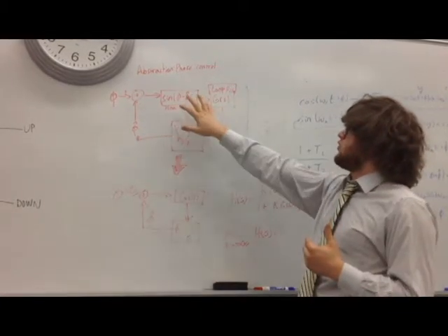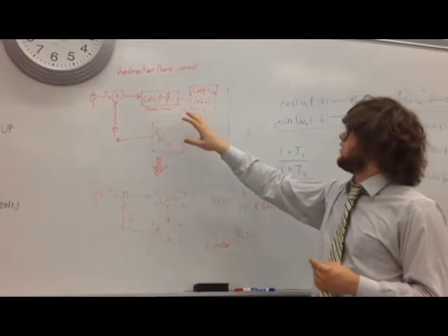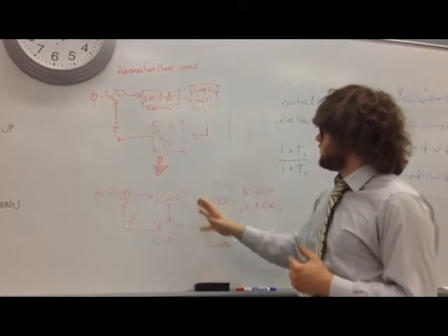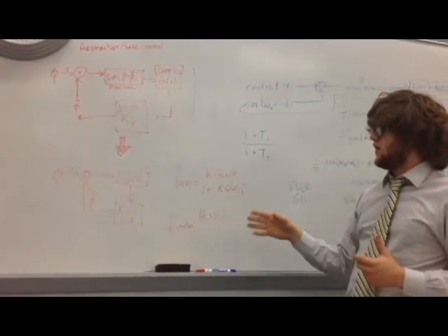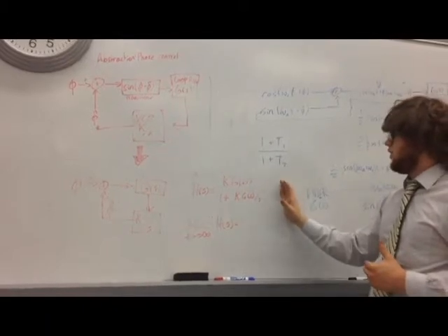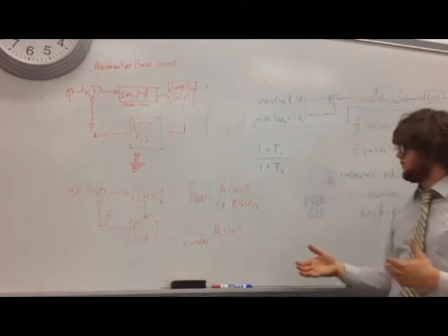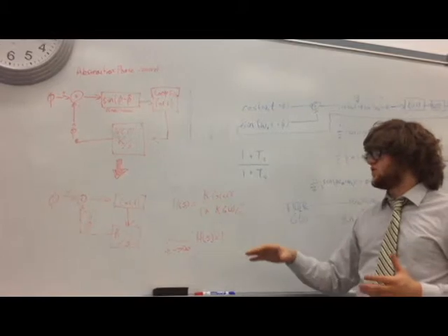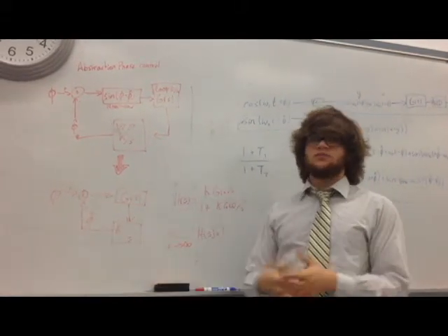Because this is nonlinear, but those phases are very close to each other, the sine is very close to its argument, which means we can take away the sine and simplify this system so that it is a linear system. Because it is a linear closed loop control system, we can describe it by this control function, which describes any closed loop control system. Over time, this will tend toward a transfer function of 1, meaning that the input and the output are equal.